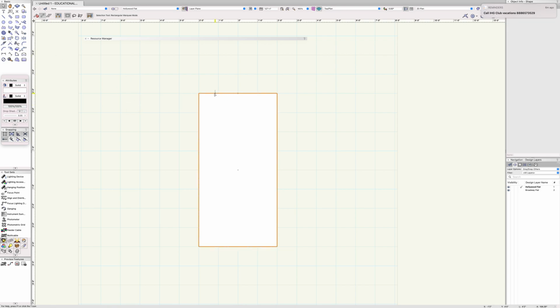So we want to draw a toggle which is 4 feet in width, and then the height will be 3/4 of an inch. So let's draw another rectangle which starts from this corner and comes to the last end. You see the x-axis already has 4 feet, so I don't want to change that. If you hit next tab, that will give you y, and that is 3/4 inch. Enter, enter. So this is your first toggle.